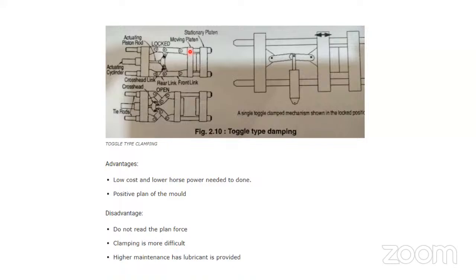One minute, sir. Actually, with this knuckle arrangement, once it is made straight, after that we normally give the tonnage and set the tonnage. While setting the tonnage, at the backside there will be a chain link, along with a hydraulic motor. So whatever tonnage is required, once set, it will be the constant tonnage. Only the link will open and close. That is what we normally set in a knuckle. Without that, we cannot operate.